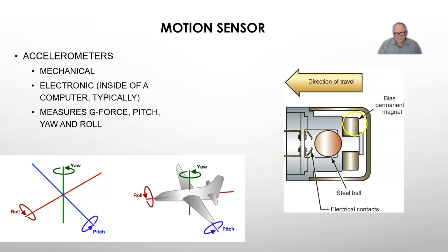They were really low tech, but they are specific for the vehicle. How much weight is the vehicle? How large is the crush zone in front of the vehicle? Where is this located on the vehicle? That would determine what size magnet they'd use, what size steel ball they would use, how far the steel ball was from there, or the amount of G-force to make it move forward.